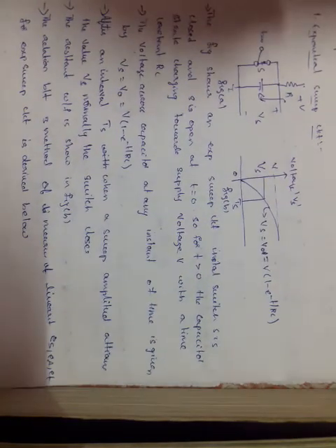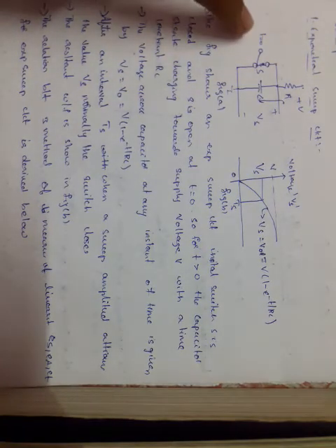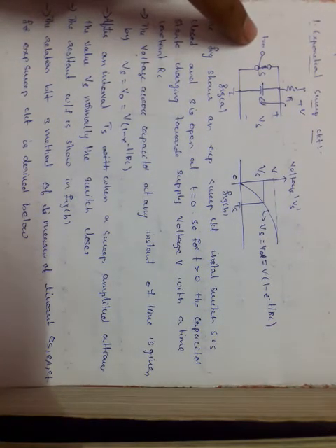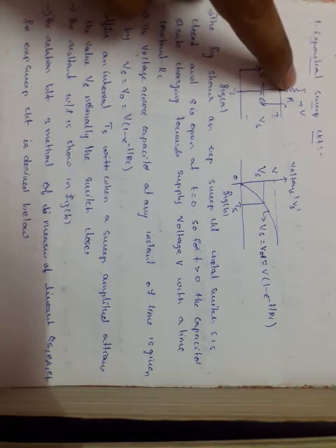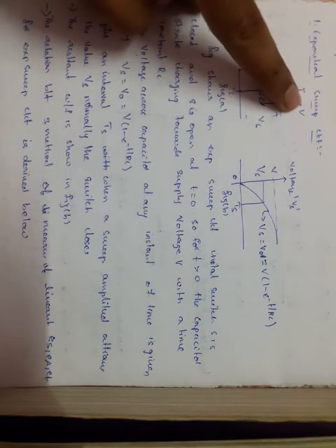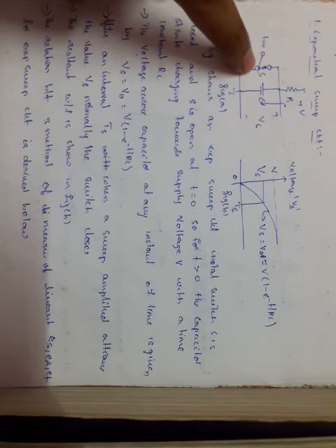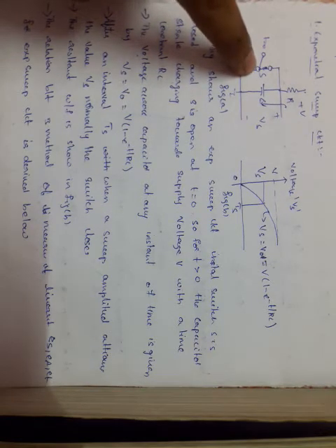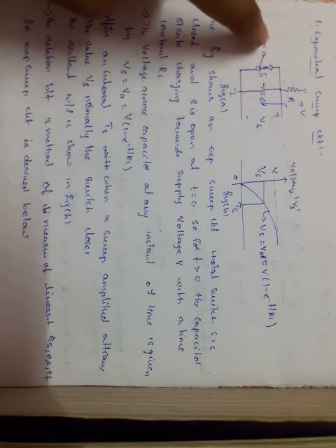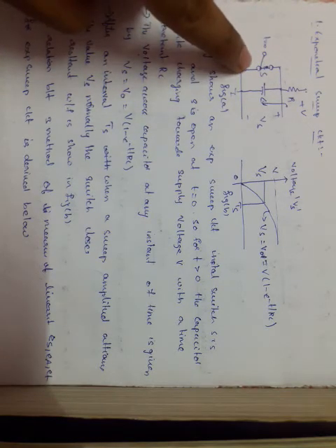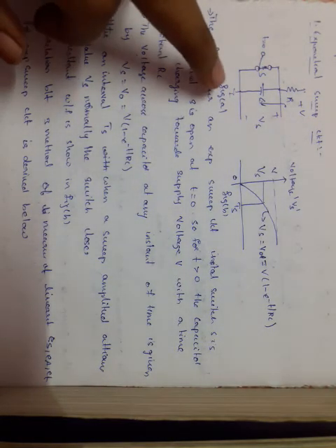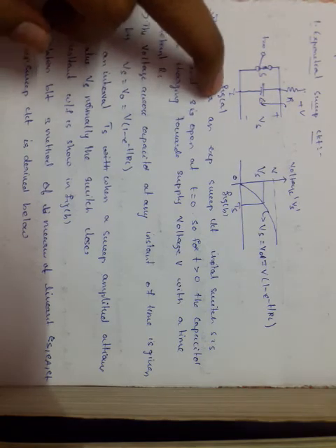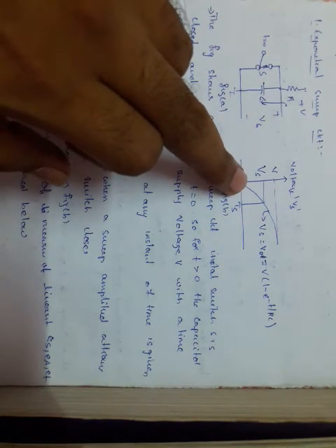The exponential sweep circuit is in this form. In this circuit, we have taken the capacitor C, resistor R and supply voltage V. Next we have constructed a switch S also. So this is the simple design of the exponential sweep circuit. After designing, we have marked this circuit as figure A. Next, let us discuss how the output waveform will be generated.